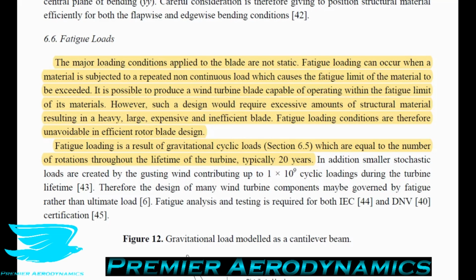So what they say is, we just let it fatigue and we figure out how long it would take for it to fatigue, and then we replace it before then. Interestingly, there are some materials out there that you can load as many times as you want, and it will never break. Some materials have a reduction, so if you bend it more and more, they will get to a point where you can put in almost no force and it will break.